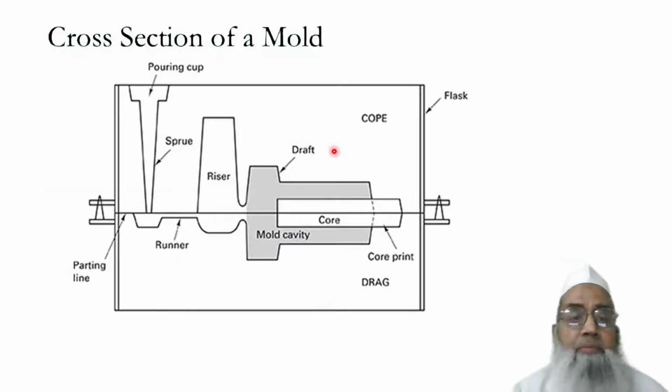However, with metal casting, primarily the initial and basic principle is by having a route through sand molding or sand mold casting. Here is a cross-sectional view of a mold. The flask has two components. The lower one is known as the drag, the upper one is known as the cope, and this is the required component.